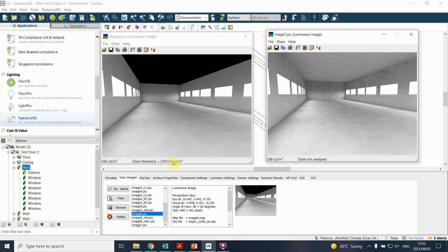So we can look at the differences between light. What they've done is there's a number of indexes for glare that you'll see this program uses, but on a very basic level, what's simply stated here is that it takes the average luminance of a space and says that glare would be experienced at 7 times that luminance. That actually just talks about the fact that your eye will adjust to the average, and it could be up to 7 times that you could experience some form of glare, or beyond 7 times that.